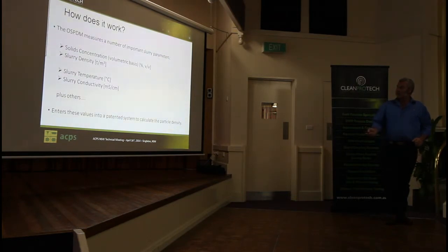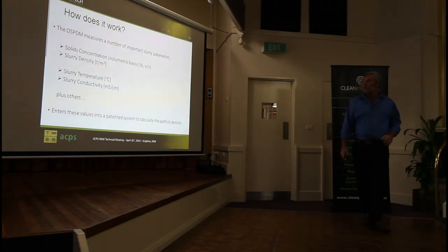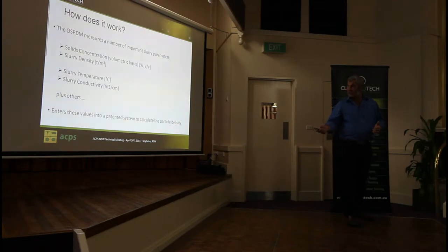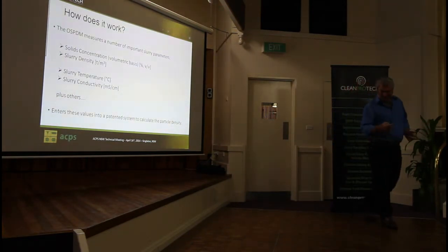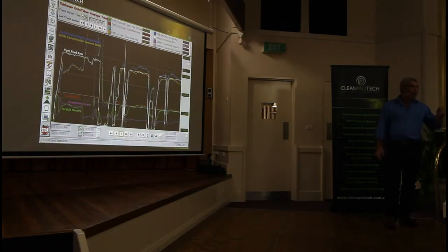So the OSPDM, what does it do? We measure solids concentration by volume, we measure slurry density, we then have to correct these densities for temperature, conductivity and some other factors that we now measure online. They improve the accuracy again, and we put that into our system. We patented a method to calculate the particle density.